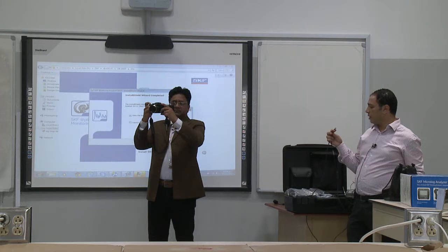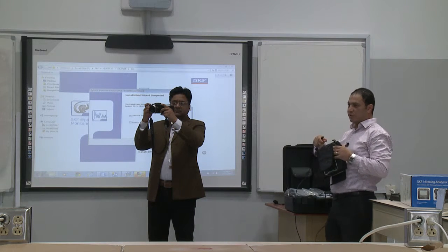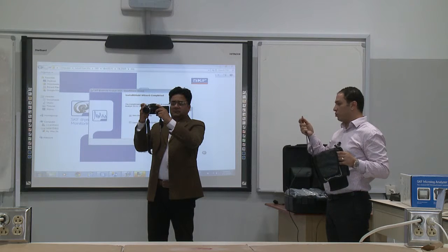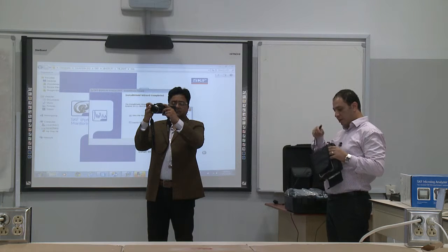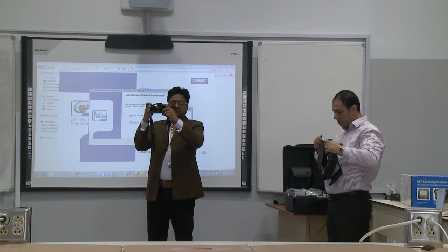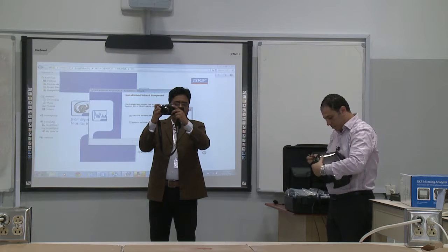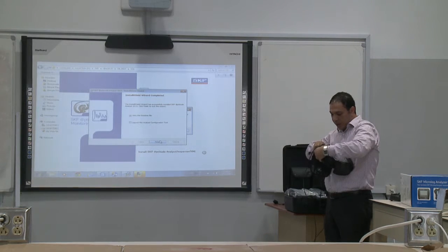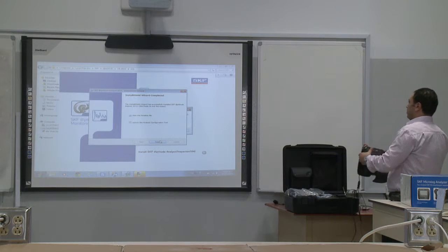This 7-pin cable, of course, connected to channel 1, which is 6-pin only, will damage the cable. So you have to be careful to look. It's 7-pin. There is one pin inside. Again, same procedure: align the red dot here, aligning the red dot, and directly mount it. You will hear the click.